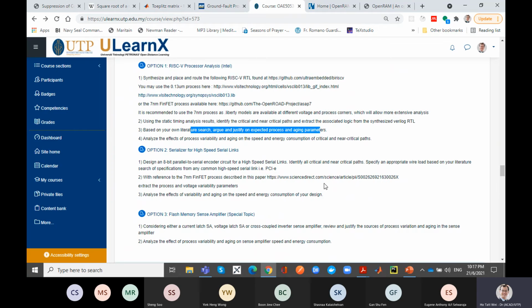Or maybe I find that NAND and NOR gates don't have as much regularity. Or maybe it's the flip-flops; I read something about flip-flops, that they are not so foolproof. Or aging tends to happen when there's maximum current. Aging tends to be like electromigration, where the areas with more current have more hotspots. So can I look at my design and identify areas where I have a bunch of large gates together?